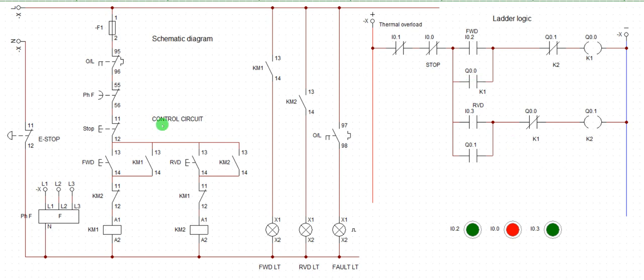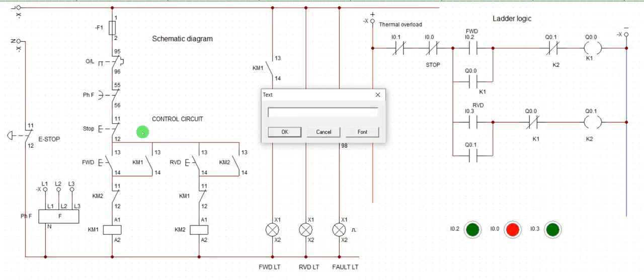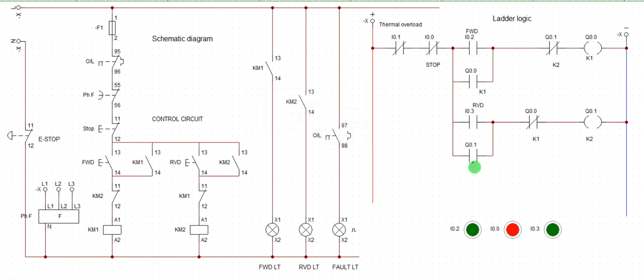All right. The same way, I have this as my K2. This is my K2. The auxiliary contact of this belongs to this. Once this one closes, the auxiliary will latch this. So this one is the latching function. This one is doing the latching function. All right. So now come here. I have this latch here. These two, KM1, KM2. The auxiliary contact of this is this one, the same way.